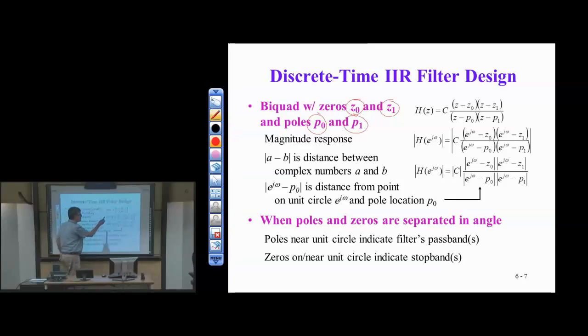You could write out this transfer function, and this is a very important representation of a filter. We can represent it in what's known as pole-zero-gain form, or PZK. This is one of many standard formats. So I have a list of pole locations, P0 and P1, a list of zero locations, Z0 and Z1, or in MATLAB, these are vectors. And then finally, I have a gain term, which is C.